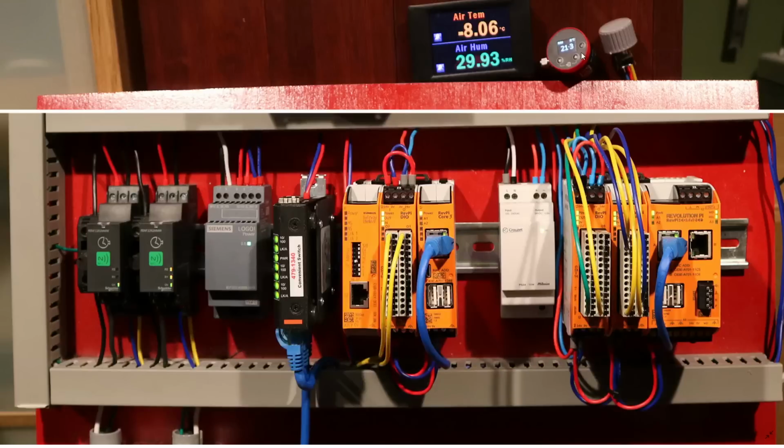The next thing that's connected is, internally right here, an infrared temperature sensor from RS Components that is measuring just the ambient temperature here. It's actually just pointing at this piece of wood behind it in this view, and it's contactless, so it's showing you that effectively the surface is 21.3 degrees centigrade. It is configured to give a 0 to 10 volt output based on a temperature reading of 0 to 100 degrees centigrade.